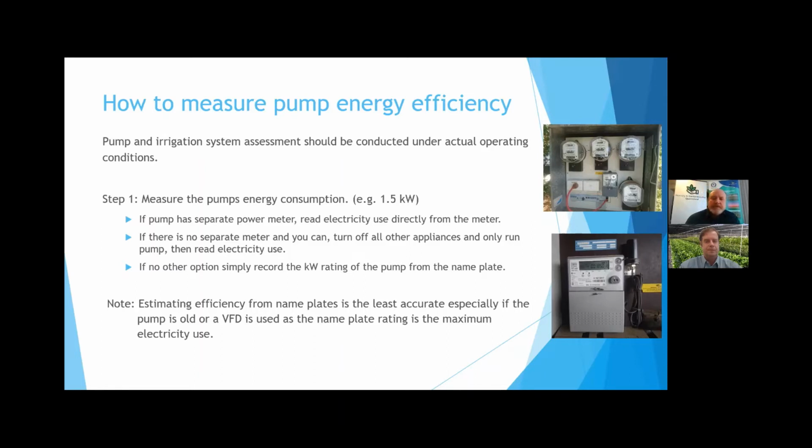So you measure how many kilowatt hours your pump is using, record that. If there is no separate meter, and you can, turn off all other appliances and only run the pump and read off the electricity use.